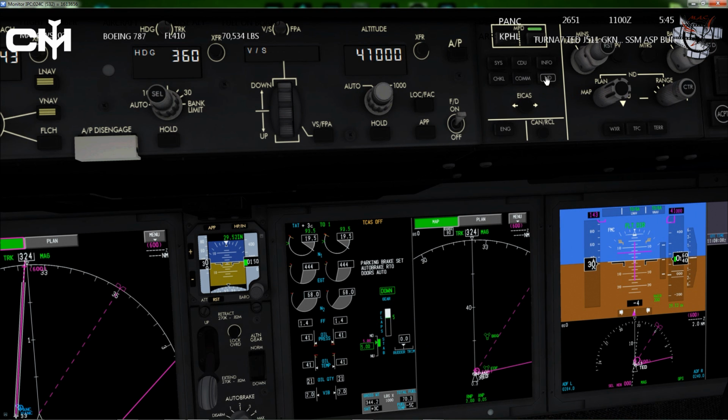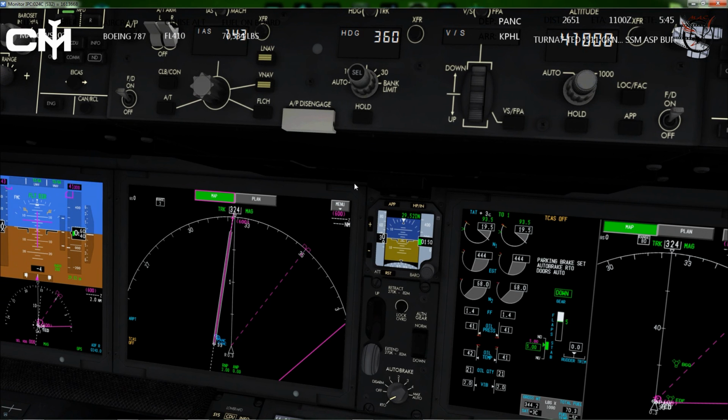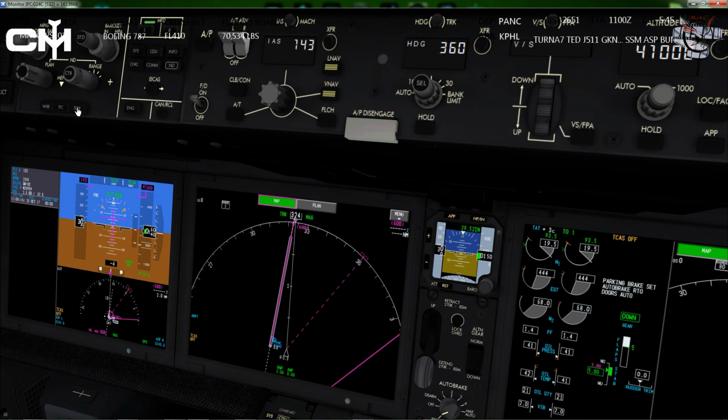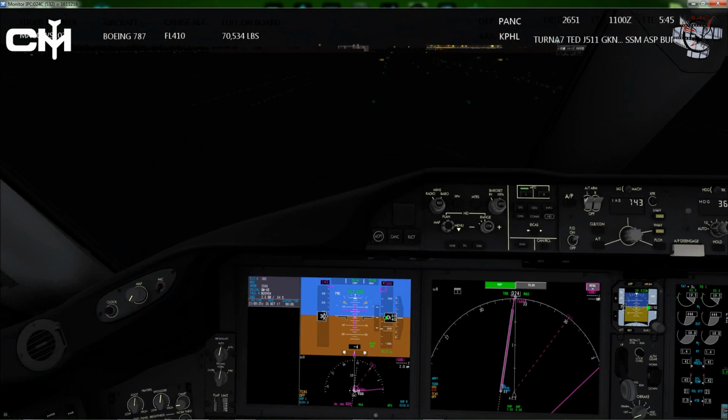That's already good. So click normal again, and that'll be our after takeoff checklist, which we don't need at the moment. So we want that on nav display. We do have some terrain around here that I just thought about. So again, I can hit terrain over here, or I can click on menu and select terrain here. And the weather's not bad, so I don't think we need to worry about selecting weather or anything like that. And hop back up here.